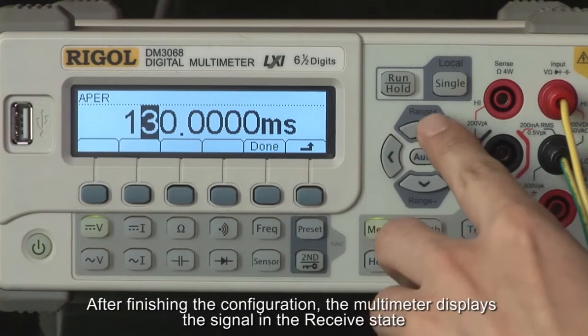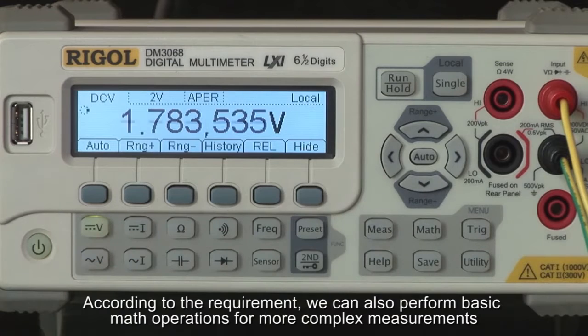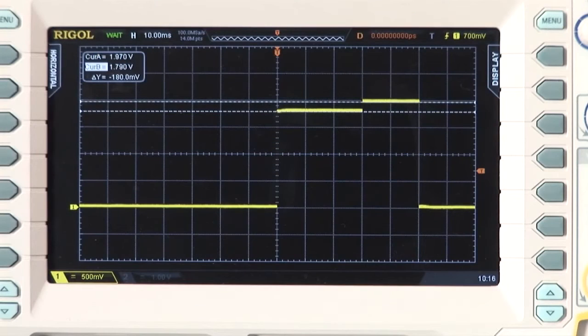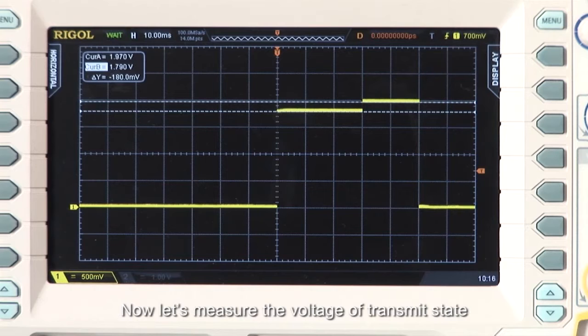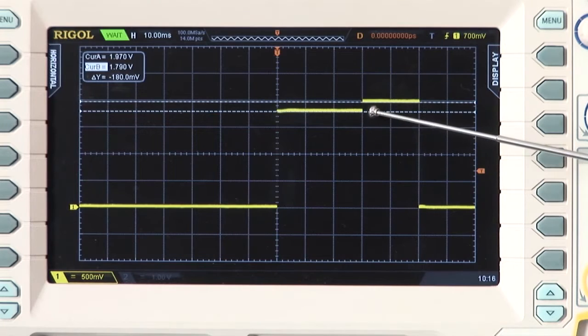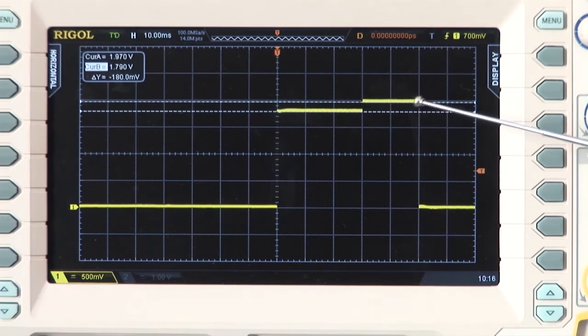After finishing the configuration, the multimeter displays the signal in the receive state. According to the requirement, we can also perform basic math operations for more complex measurements. Now let's measure the voltage of the transmit state. Recall that the transmit state begins 30 milliseconds after the trigger point, and the integration time should be set to 20 milliseconds.